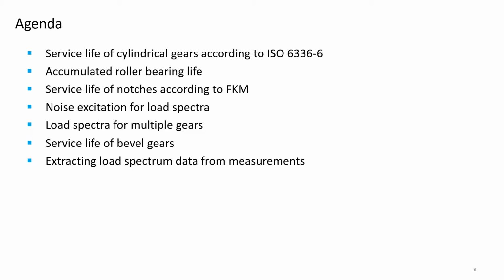So today we will start with cylindrical gears and service life according to the ISO 6336. We'll then move on to accumulated roller bearing life and service life of shaft notches according to the FKM guideline. We'll do a brief excursion into the topic of noise excitation and the possibilities you have here to consider varying loads via the load spectrum.